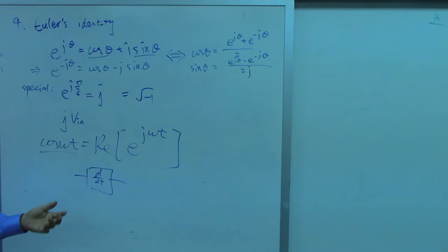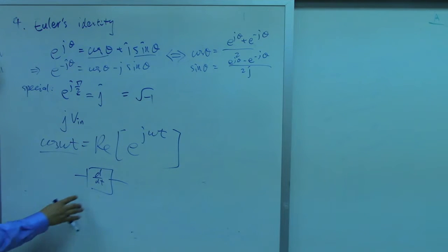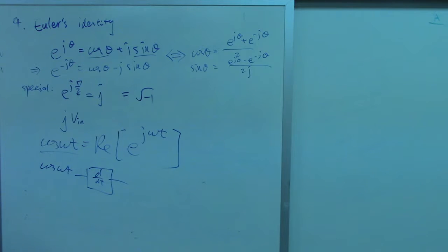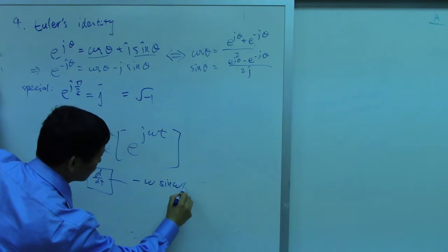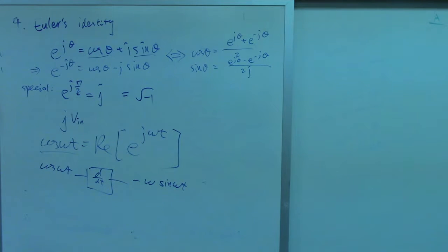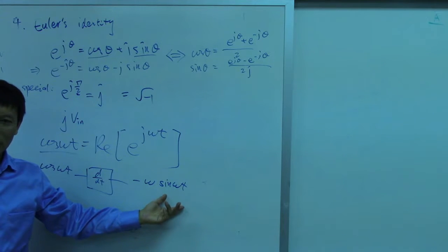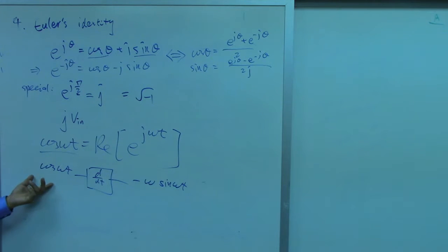We know how to implement a differentiator in a circuit, right? Have you learned any differentiation, integrator? This is supposed to be in 311, operational amplifiers. So this is a differentiator. If your input is cosine omega t, what is your output? Your output will be equal to negative omega times sine omega t. Make sense? Now you look at the input and the output. The looks are different. This is a cosine function, this is a sine function. So it's not easy to represent the output with the input.